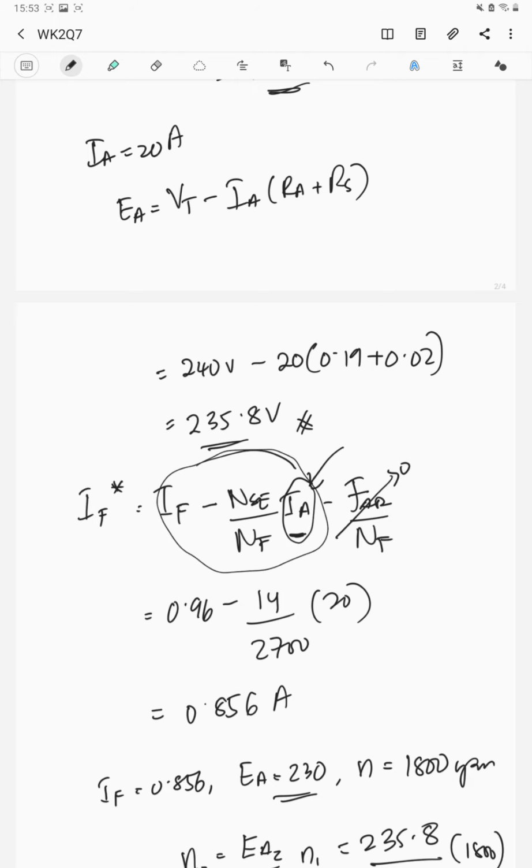So the motor will either typically remain still or slowly turn in the wrong direction while burning up because of the excessive armature current. So if we happen to start this machine, the series field must be short circuited so that it behaves as an ordinary shunt motor during the starting period.